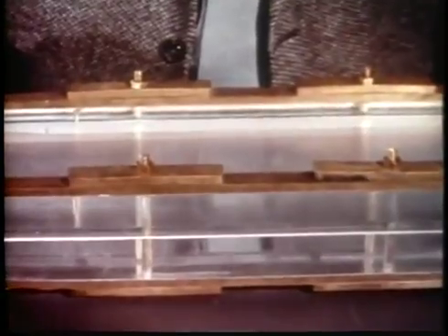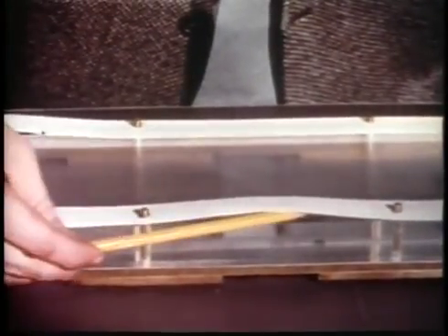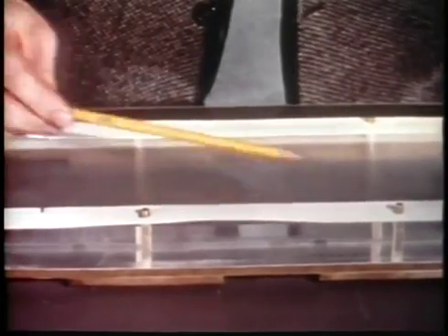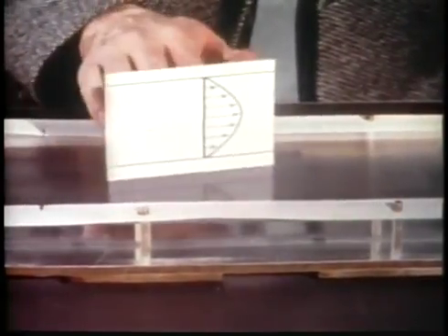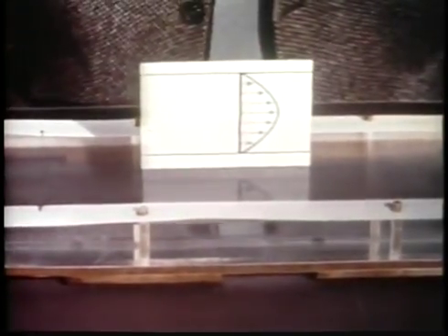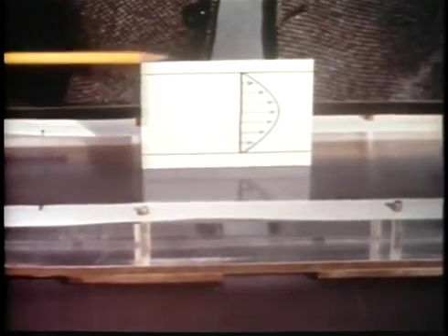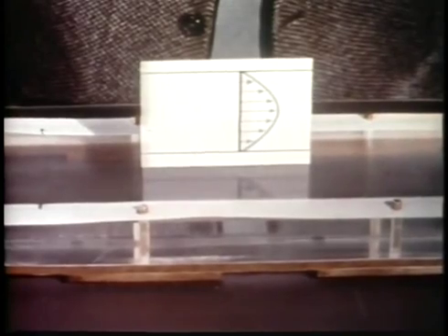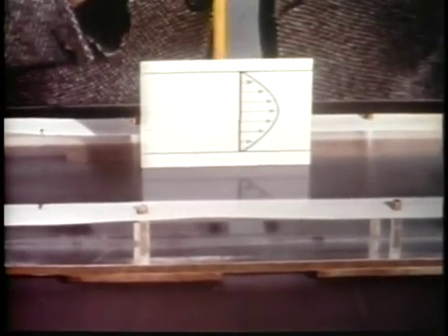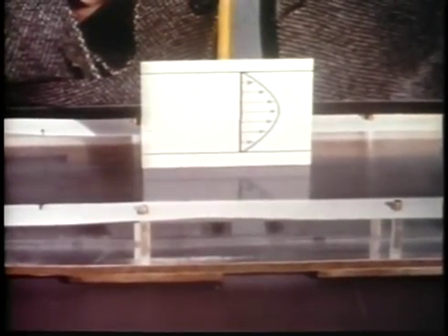The gap between these two thick plastic plates is formed by this gasket. When fluid is forced to flow through the cell, all particles in the same neighborhood are subjected to the same pressure gradient. The fluid velocity varies, being zero at each plate and a maximum midway between them. But at all points on a line perpendicular to the plates, they are moving in the same direction.